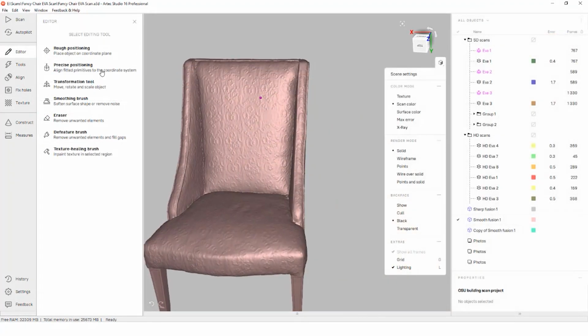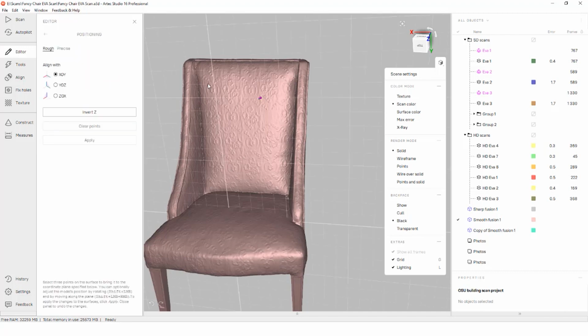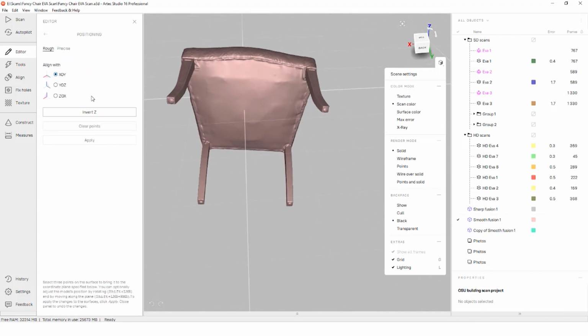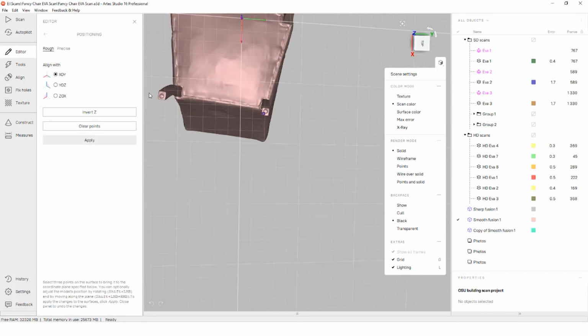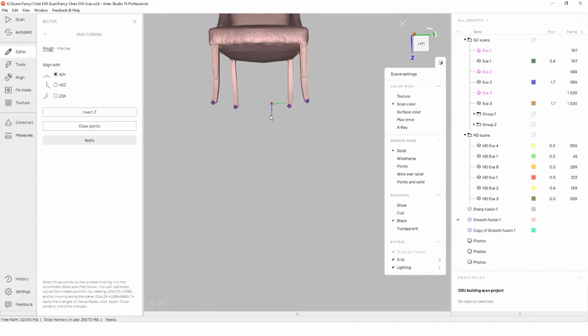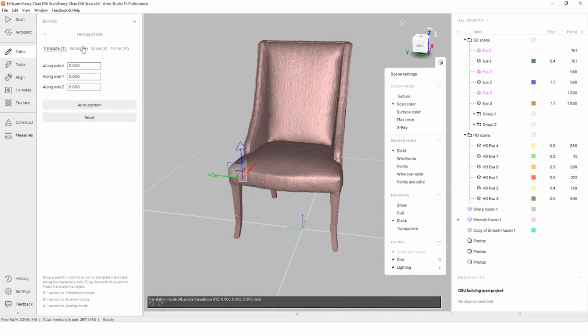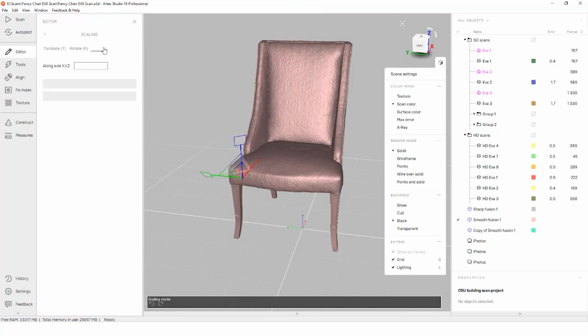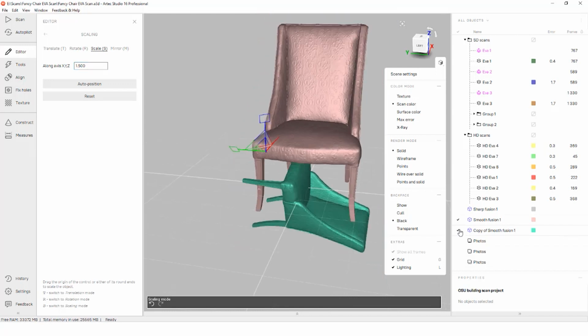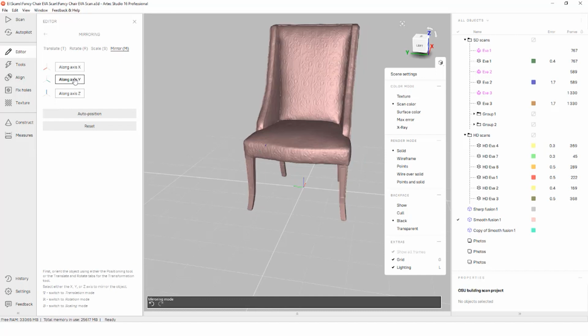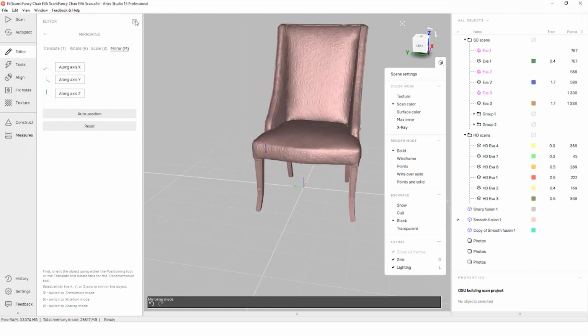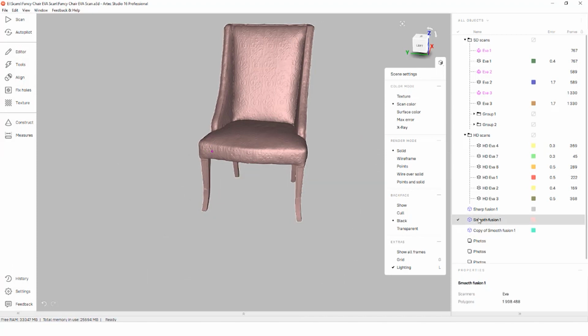Now at this point, we've done all the changes to the mesh itself, and we can start aligning it to a new coordinate system before exporting. Back in the editor tool, we can go through a rough position to quickly establish a Z-plane of our mesh using some control points. This tool is handy for quickly positioning scans for prints or possibly a starting position for reverse engineering. There's also a set of transformation tools inside the editor. This allows us to make fine adjustments to the position of the mesh, or even mirror and scale it to a new size. This can be done with meshes imported into Studio as well. Other editor tools such as Defeature or color and painting can help patch up specific areas of the mesh too.